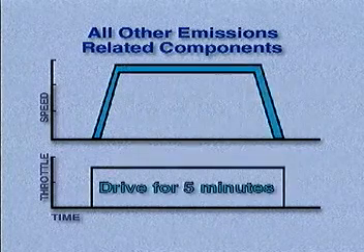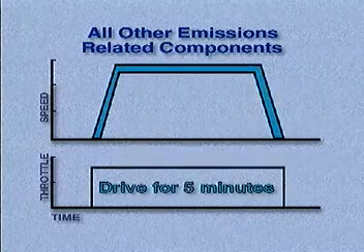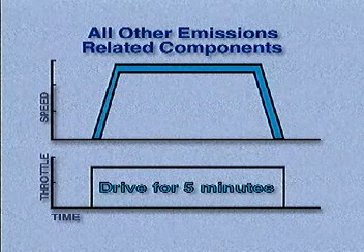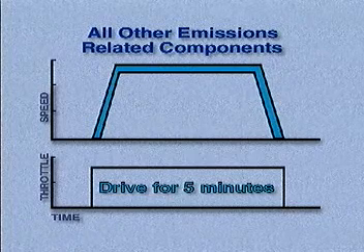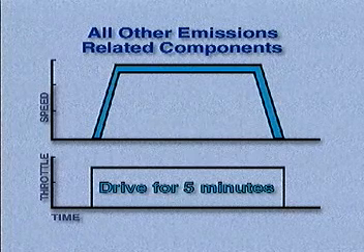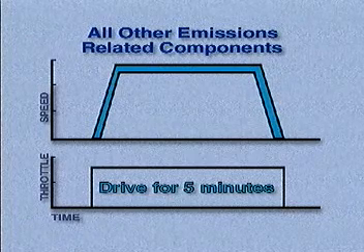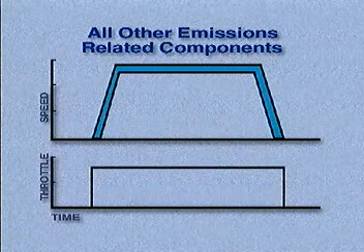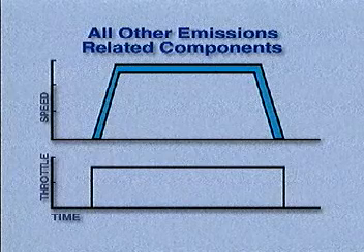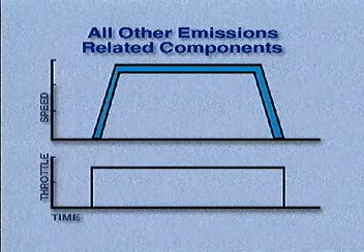Drive for 5 minutes at this speed using D range for cars equipped with an automatic transaxle or fifth gear with a manual transaxle. Minor acceleration or deceleration is not a factor during this test, and slight braking is okay. Come to a complete stop and shift to park with an automatic transaxle or neutral with a manual transaxle.